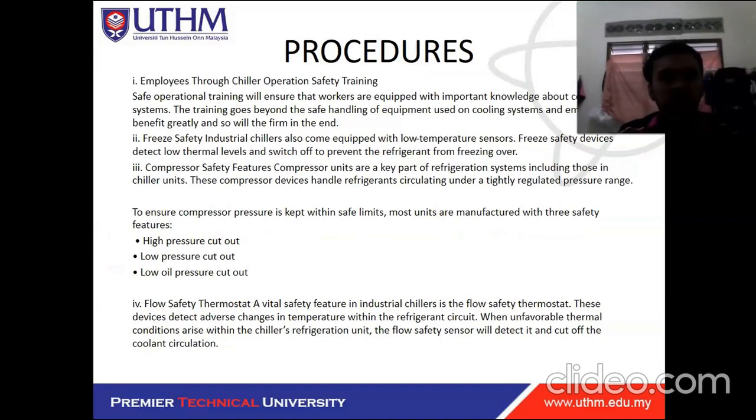And the procedure is our simple procedure. First, we want to include freeze safety. An industrial chiller can also be equipped with a low temperature sensor. The freeze safety device detects a low thermal level and switches off to prevent the refrigerant from freezing over. And then the compressor safety features.